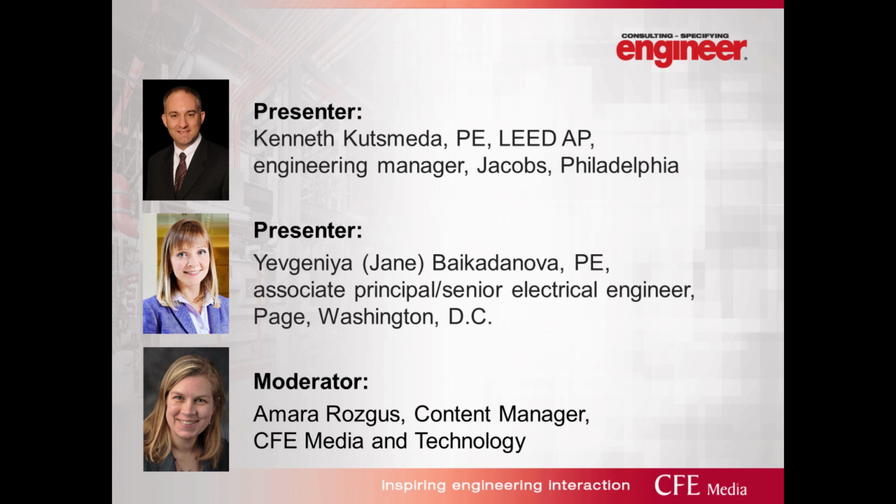Well, Amara, this is a great question. I just finished a project where we replaced the lead-acid batteries with lithium-ion batteries, and that was done in a state where we needed to meet the NFPA 855 requirements. Depending on what jurisdiction you're in, whether you're following IFC 2015, IFC 2018, or NFPA 855, there are different requirements for the lithium-ion batteries.